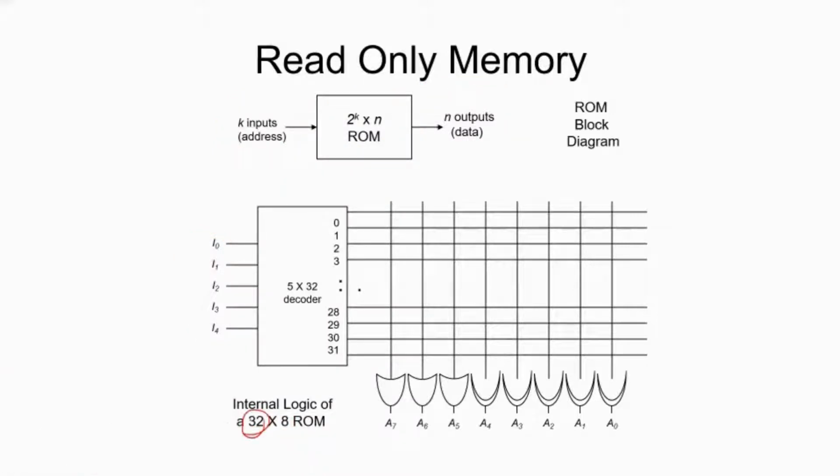It's a 32, so we again need a decoder. For the purpose of ROM, as I talked about it also, 1D decoding is usually done in the case of ROM. Then again you have this decoder. Now how it works in this manner. This 32 is the number of addresses. 32 means actually 2 to the power 5, so you will be having 5 address pins. You'll be needing a 5 to 32 decoder.